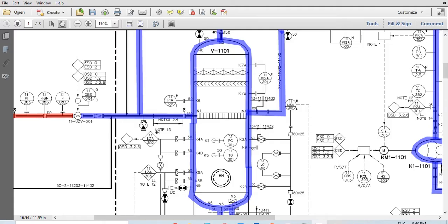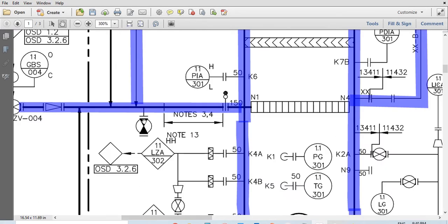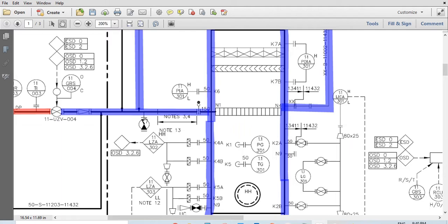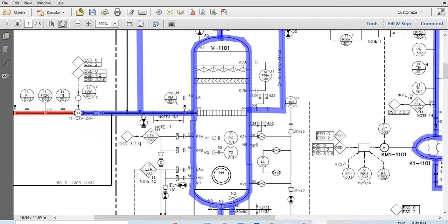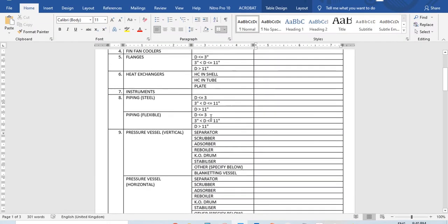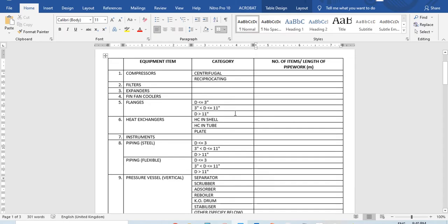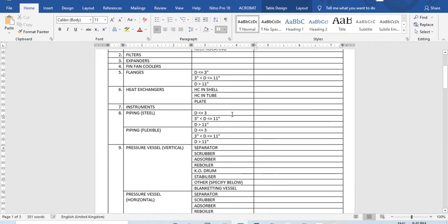And here we have a flange, which should be this line. I wouldn't be able to know what this line is, but I guess it's bleeding. It should be some sort of line to bleed the line. So this would probably be about a 2-inch line. If your P&ID is more detailed, please put that in there.